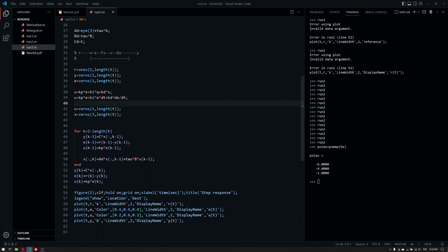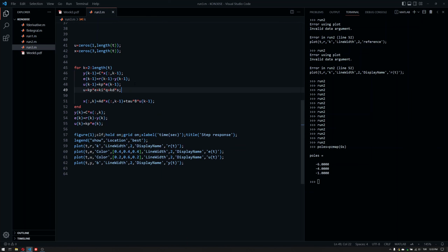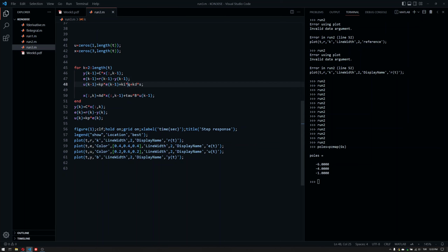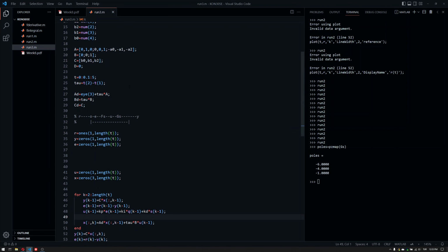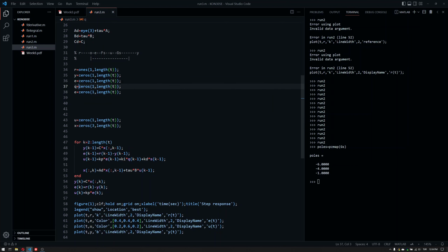And we're just going to take the linear combination. If you know the meaning of q and s, you can just see that the controller just is a linear combination of those three signals. So it means that our control signal here, which is going to be this one here, is going to change a little. And in fact, it's going to add two additional terms. I'm going to add ki times q and kd times s. So I've updated my control signal now. So this portion here is updated. But we need to generate the required signals from E here. So let's also call them q and s.